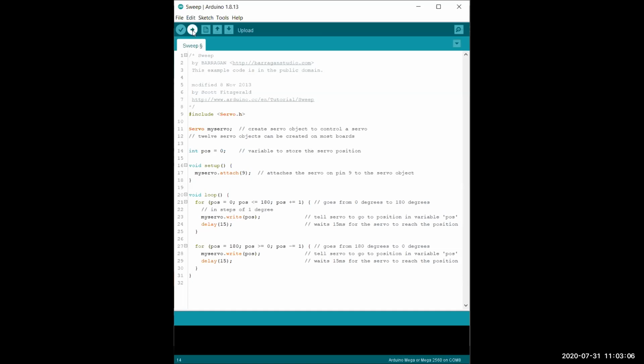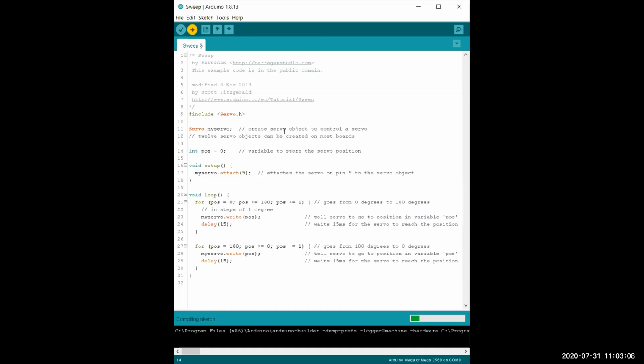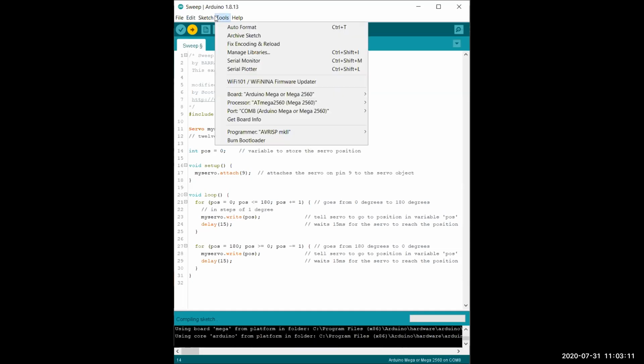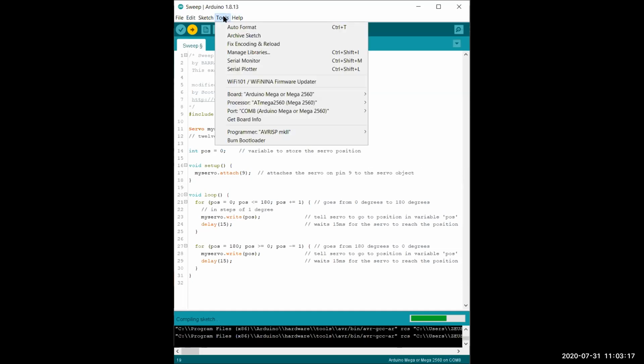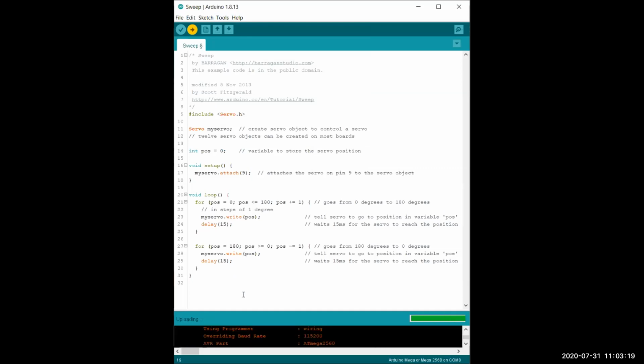So upload. Like I said, always make sure you have the right COM connected, and then click upload. You'll see it will do this, and then it will say finished. Just look at Lillian's video, you're going to see what it's doing. If you do the connections right, this is what it should be doing. It should be rotating clockwise and then anti-clockwise, clockwise, anti-clockwise, okay?